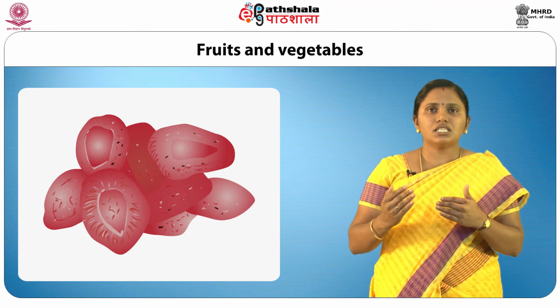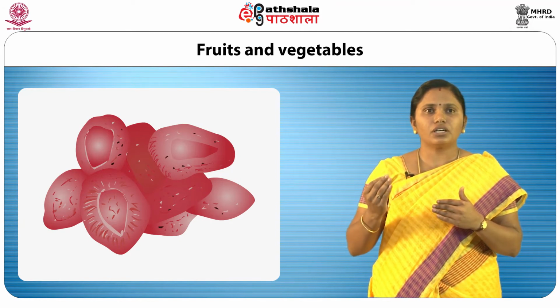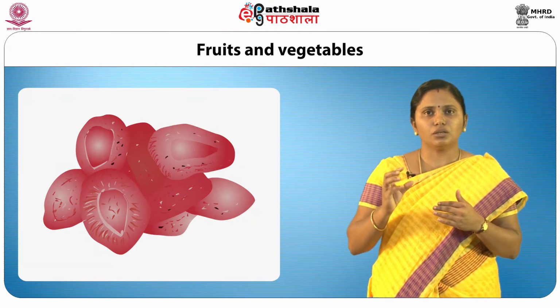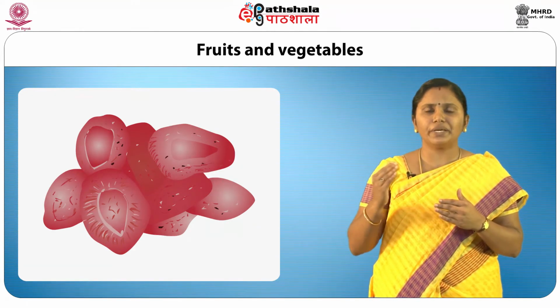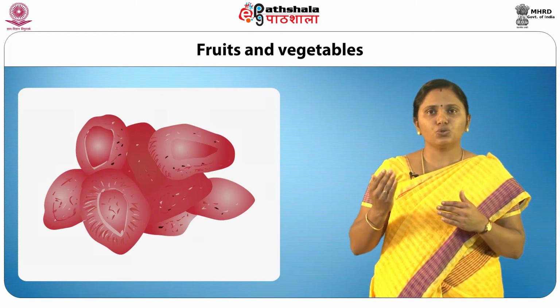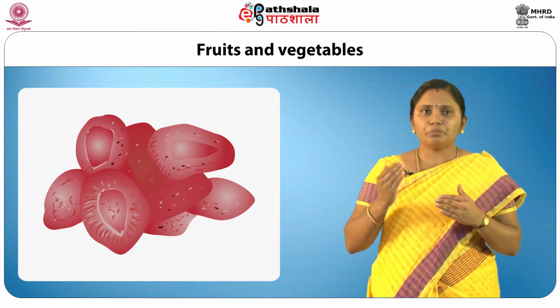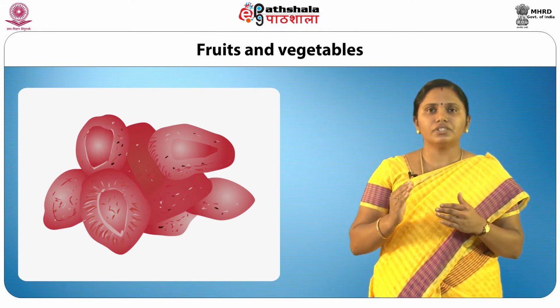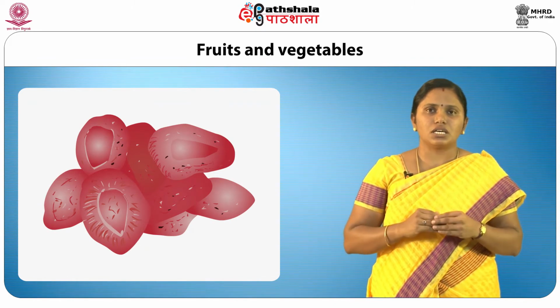The white varieties of mushroom are preferred for freeze drying, pigmented varieties tending to shrink more. They should be peeled, sliced and blanched before being loaded into trays. With a plate temperature of 82 degrees Celsius, a drying time of 3 hours is possible for this type of materials.